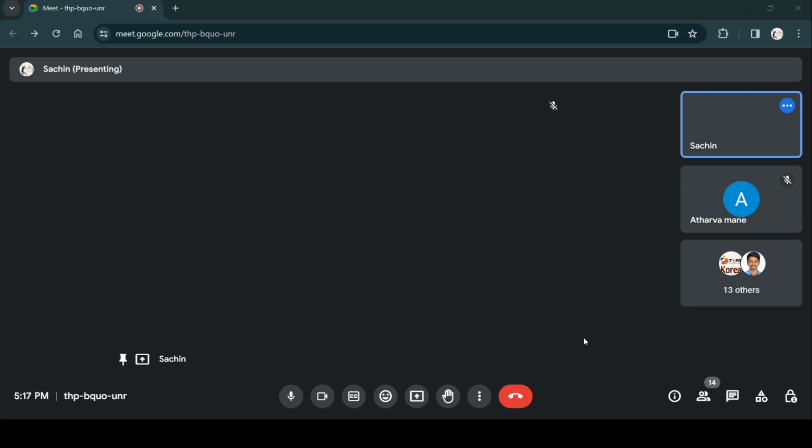So D and A more accurately mark the cutoff points. Before this, T2 will be in saturation, and after this point T1 will be in saturation. So point A marks the transition point when T1 goes from off state to saturation, and point D marks the point where T2 goes from saturation to off state.